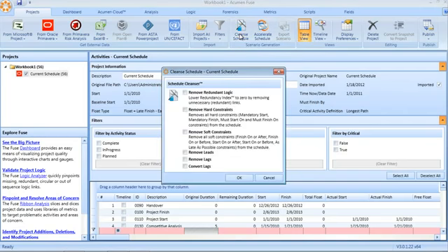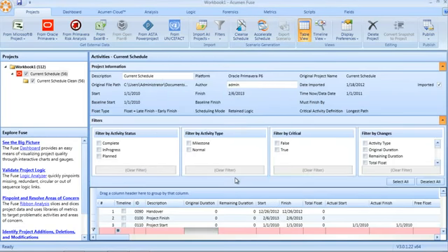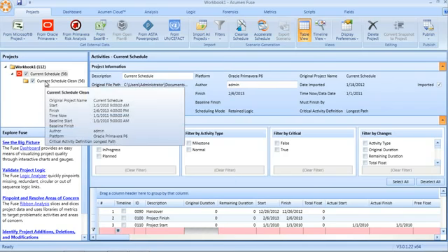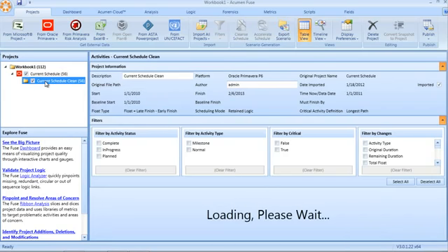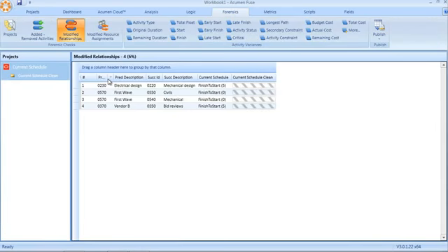Through the Schedule Cleanser, I can simply click on Remove Redundant Logic. Fuse will then run an analysis. It will remove those redundant links and create a scenario. By using the Forensic Analyzer, that scenario can then be examined, and as we can see here, we can see the removed logic links relative to the original schedule.